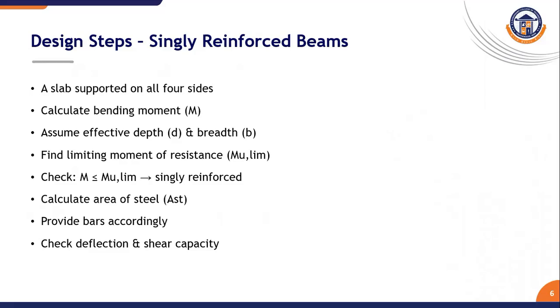Design steps for singly reinforced beam. The design procedure has the following points: calculate the bending moment from loading, assume breadth and effective depth, find limiting moment of resistance. If demand is less than the limit, design as a singly reinforced beam. Provide required tensile steel, check shear, deflection and detailing as per IS 456.